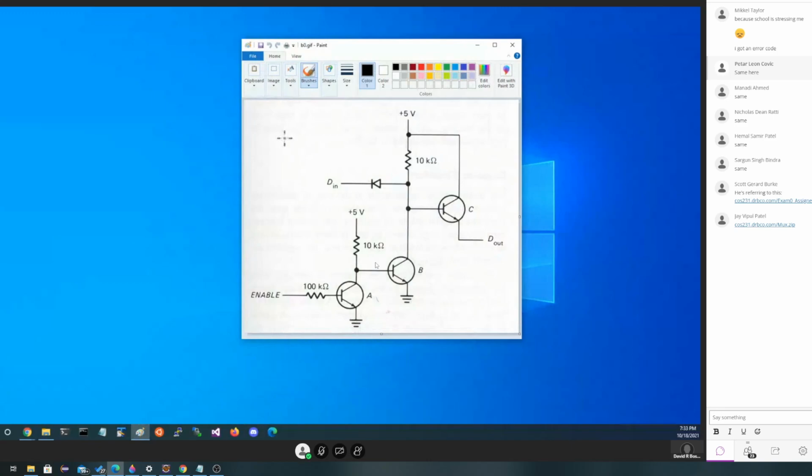This has something in it which we call tri-state logic. So the Boolean output here is going to have one of 3 values, not 2. It's going to be either a 0 or a 1, which we know about, or just like the open collector when it wasn't connected to the bus, it's going to be in what we call Z state. Z stands for high impedance. Z is the symbol for impedance. And high impedance basically means I'm not here.